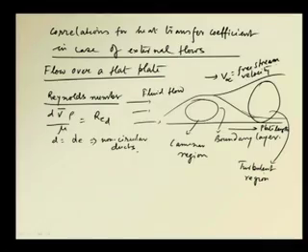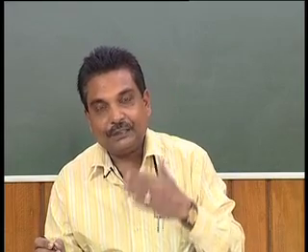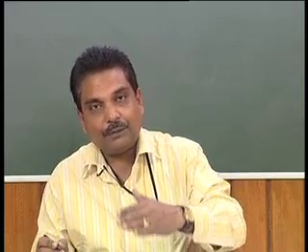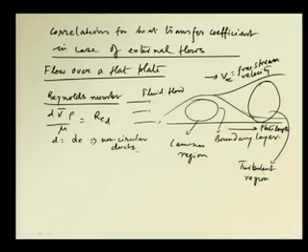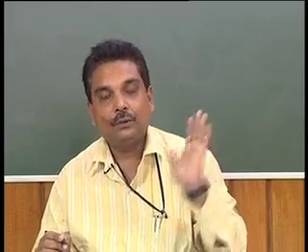Already we have discussed a little on that. Free stream velocity means the velocity of the stream which is free from the effect of the wall. That means any flow beyond this boundary layer has a velocity V infinity; beyond the boundary layer, it is free stream. So, here the velocity remains constant. In this region, the fluid is not affected by the wall. That is the main consideration here.